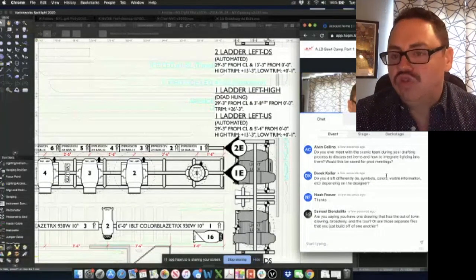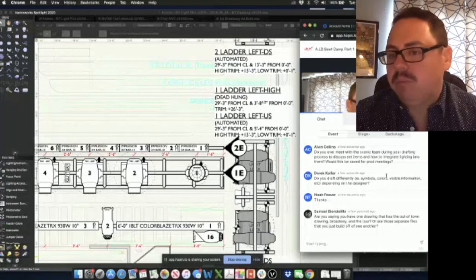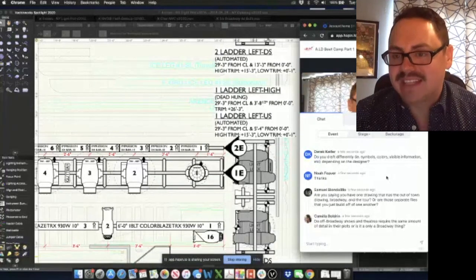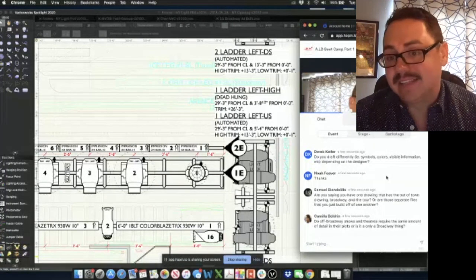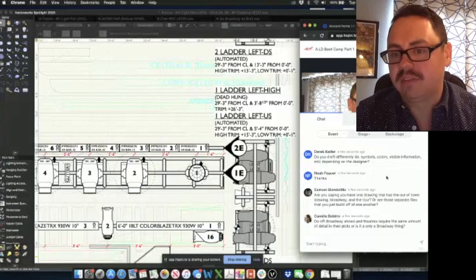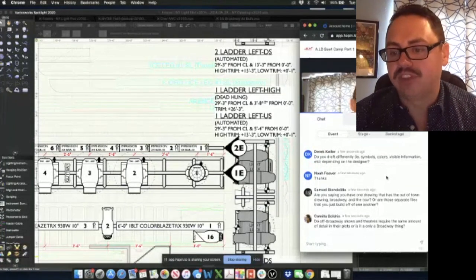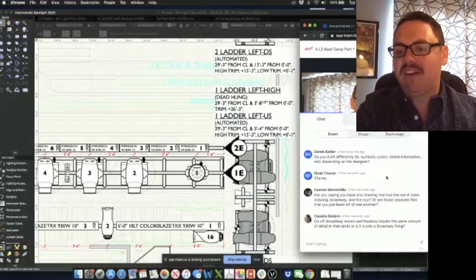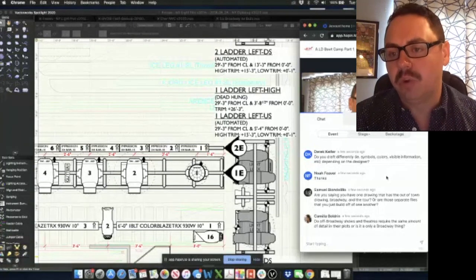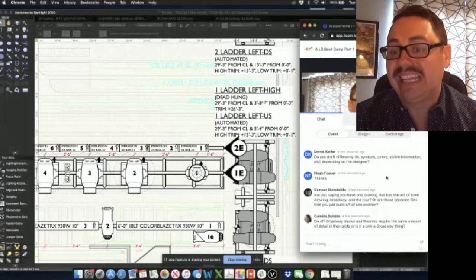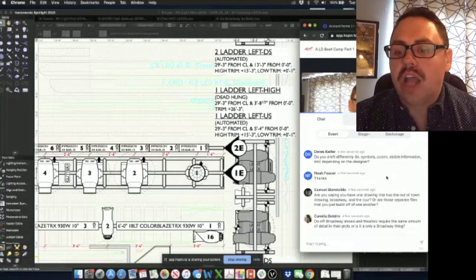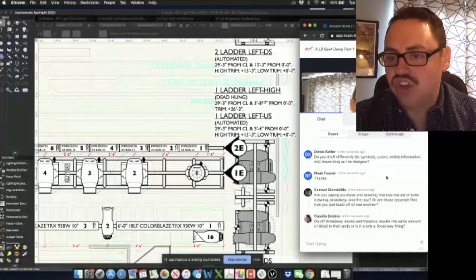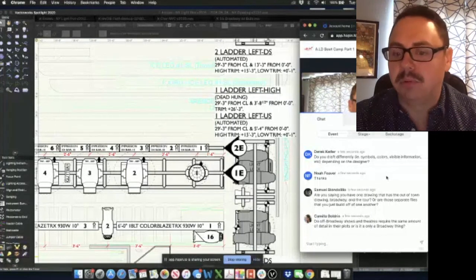If I get a new drawing from Scenic, sometimes I will import the whole thing and put it in there. I'll check and see if any of it affects the things I've done. And if it doesn't, sometimes I don't import all those things to it, so that I'm not muddying my drawing. If I find a big change, then I only have to go in and, like I said, I spend that whole day cleaning up their drawing. So I don't have to change the whole thing. I can just choose the section that has changed and clean up those few things to implement them into my drawing.